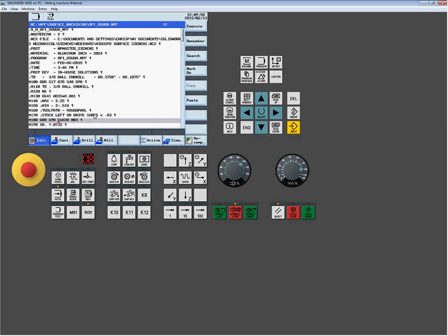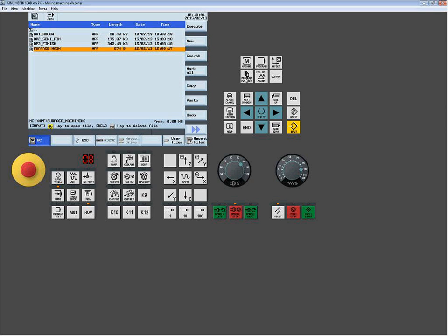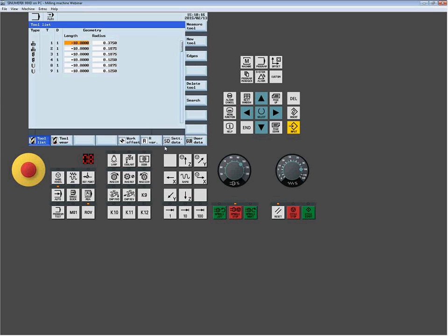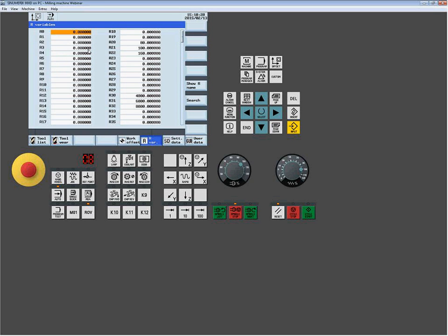It's going to be if the main program is seeing it. So what I was doing before in my little program is right here with my R30, telling this thing I want it to run at 4,000 RPM. There aren't any values set up in your part program. What this automatically does is go over to the offset table, go to R variables, and look for R30 in this column.